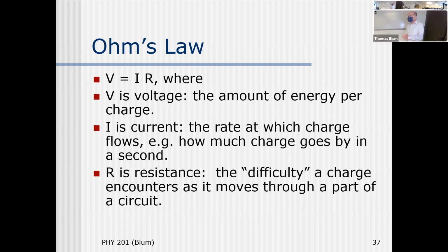All right, so we're going to work with Ohm's law. If you've played with lab 1, part C, then you know that if the voltage divided by the current stays the same, if it's always a constant number, if it goes from 2.7 to 2.69, that's not a change.